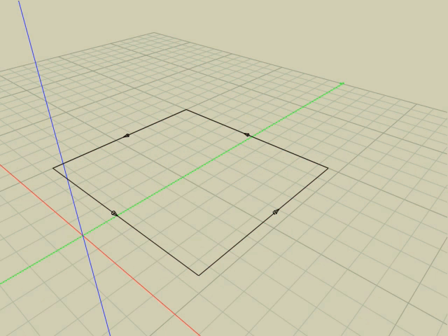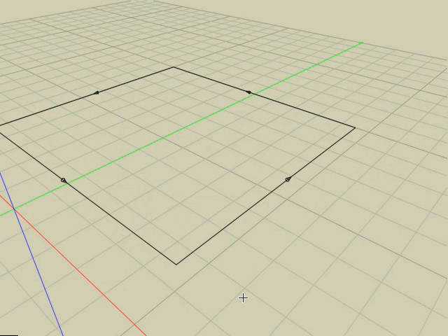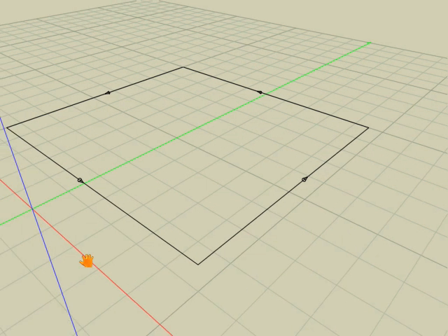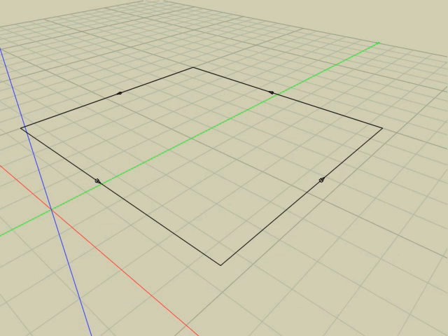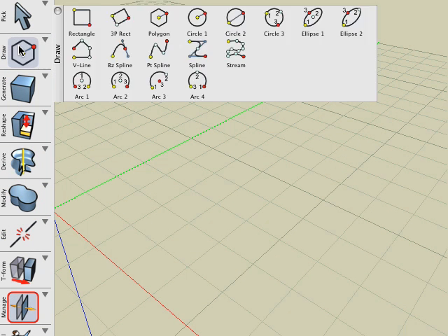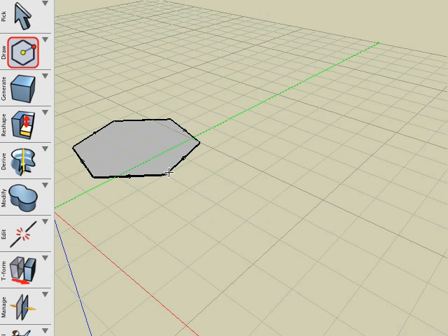How is this operation useful? More or less the same way as the Set First Point is. Using again the lofting example, when you loft a number of shapes, you want their direction to be consistent. If they are not, this tool will correct them. With 3D solids, the Reverse Direction tool basically turns them inside out.